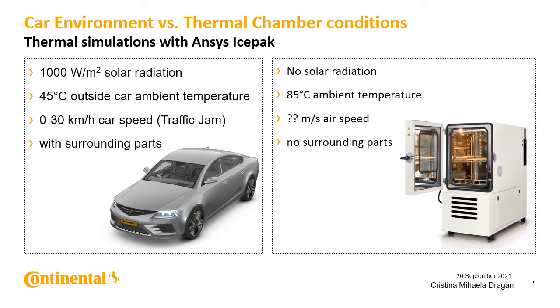For validation conditions at high temperature analyzed in the thermal chamber, there is in general no solar radiation, the ambient temperature is 85 degrees, and inside there is an unknown turbulent airflow behavior which varies from thermal chamber to thermal chamber. So the airspeed inside is unknown, and another difference is that we don't have surrounding parts. In the end, we should ensure that we are safe for both conditions.